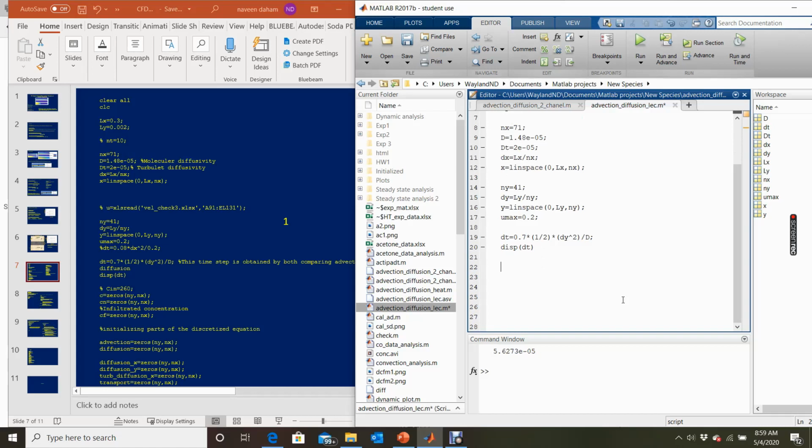The explicit finite differencing scheme is entirely dependent on the time step size. Usually, if you go to ANSYS or COMSOL or whatever CFD platform you have, they are entirely using the implicit scheme. With an implicit scheme the time step size doesn't matter; the solution will converge anyway. However, in our case we are using the explicit scheme, so we are limited by our time step size.